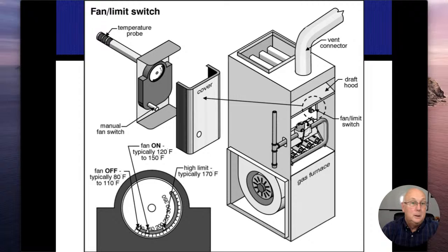All right. But again, let's say that blower fan was broken and it didn't operate. Then it would keep getting hotter and hotter and hotter until it reached somewhere around 170, 180 degrees. At that point in time, it's too hot, and that would actually turn the fire off and shut down the whole furnace and let everything cool back down again so that it didn't burn the house down, or start on fire itself.